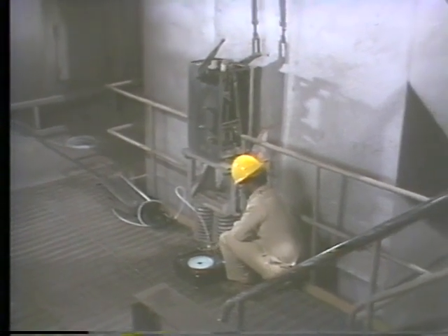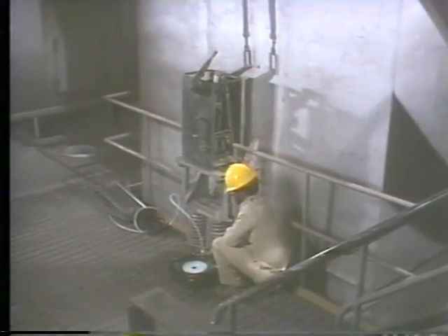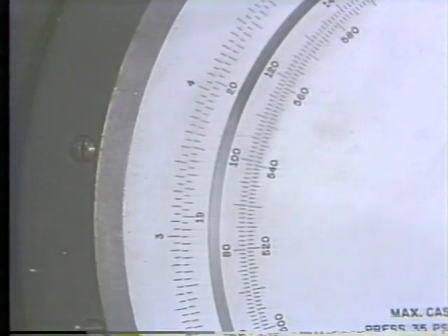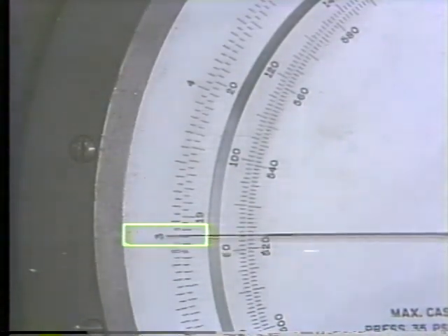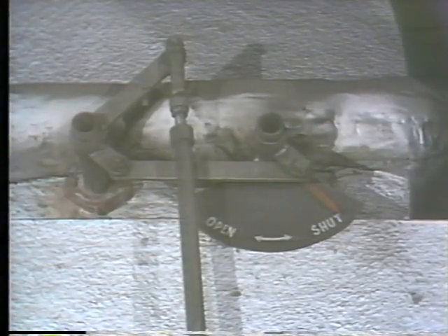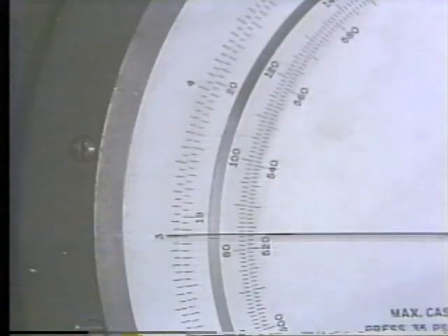Now, the range of this positioner is 3 psi for its minimum input air pressure to 27 psi at its maximum input air pressure. So the first step is to set the control air pressure from the manual loader to the positioner at 3 psi. So with the manual loader supplying a control air pressure of 3 psi, the piston and louvers should remain in a shut position. With control air to the positioner at 3 psi, the cam should indicate 0.